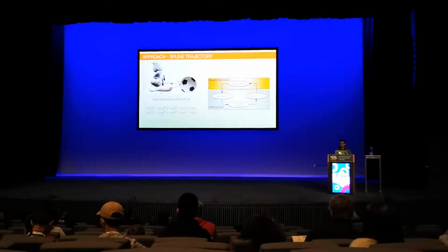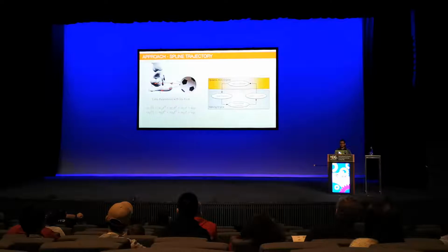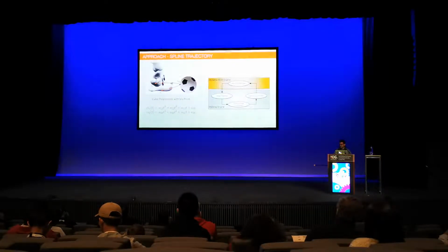And in order to do this, the step planner waits until the current foot for the kick motion is in the swinging phase. And when this is the case, the step planner sends a kick direction. And when the swing foot phase of the kick starts, the walking engine communicates with the omnidirectional kick controller to generate the kick trajectory.